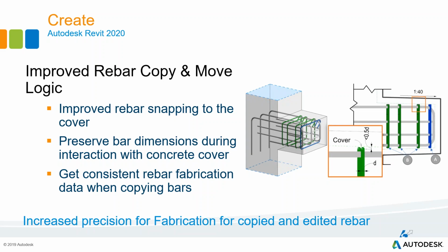This change in behavior ensures that bars will no longer incorrectly connect to faces that are far away and react to the changes of those faces. You can still manually select any face as a constraint target parallel to the bar segment, even if that face is not within the range.